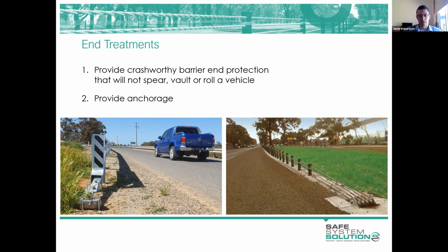Now, we're in the space these days where we're dealing with proprietary products. G4 is off the market, so there is a corresponding end treatment for every flexible W-beam product and wire rope product. They go hand in hand. You can't switch things up between different products. So it might be the case that a longitudinal product you prefer for one reason or another. Then you are stuck with the terminal that suits that product, and vice versa.